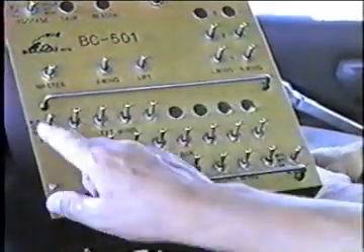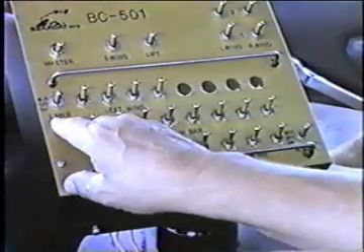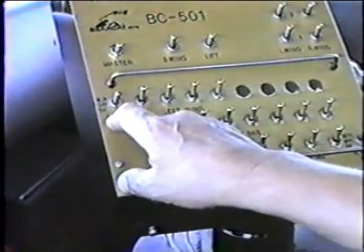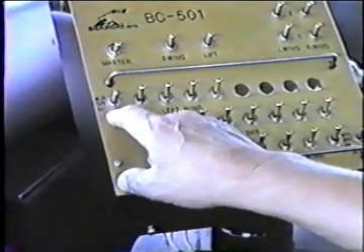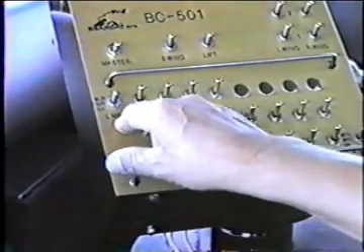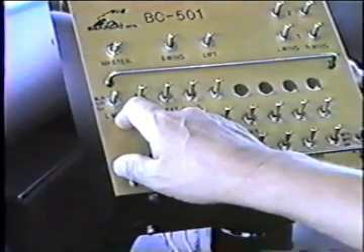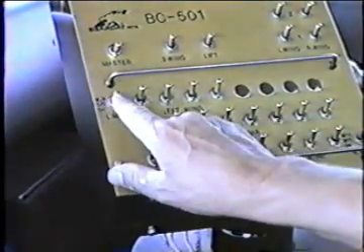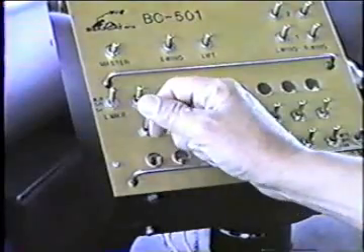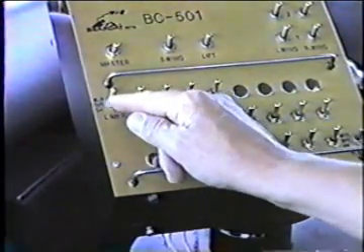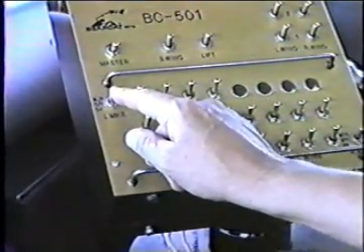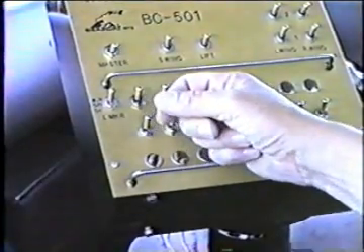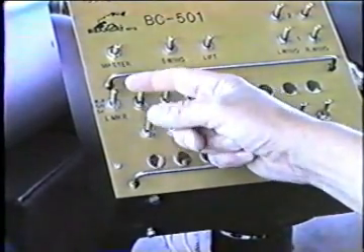Going on down the panel, got a line marker clear on the left end. Of course, that's a single nozzle on the end of the spray bar for marking out lines or for extending the width of the spray bar by one nozzle. It's a 3-position switch. Again, in the master position, anytime you turn the master switch on, that comes on with whatever else spray bar you have selected, and essentially what it does is lengthens the bar out a little bit in that situation.